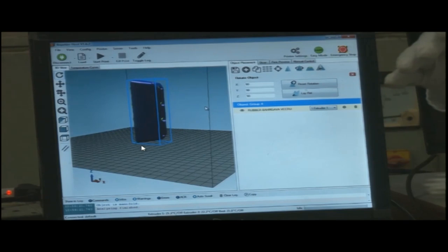When we increase height, because it is manufacturing layer by layer, this is very important to note. If we increase the height, the total time would increase. So the height has to be optimized, it has to be minimum. These many layers are to be deposited, so the total time would increase.